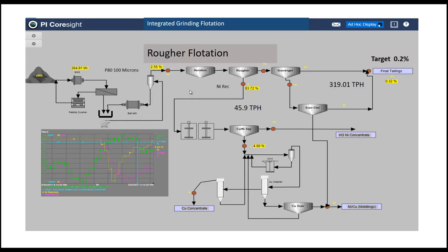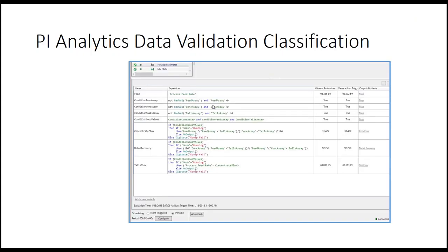And that number is predicted from a rigorous mass balance. And then again, this is a rigorous mass balance. You check, as you can see here, it is true. Then you can estimate the concentrate flow, the tail flow. And when you have that information, you can plug it into the next section, the other section. So you start predicting and you have a very good augmented system to do a lot of things that before were impossible.